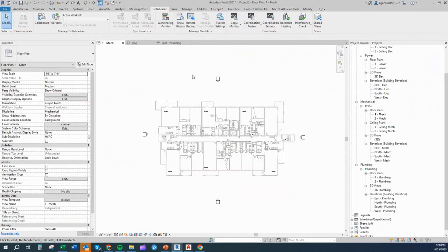This DWG export consists of making a translation of Revit sheet views to get formats which are already radically different. When working with BIM models, the ideal solution is that there is no need to export the DWG and all of the stakeholders are able to consume the BIM model. But this is just an ideal world. Actually, it is required in many cases to export to CAD formats.